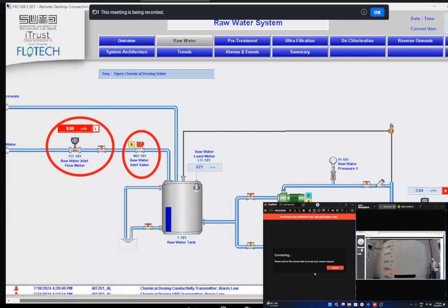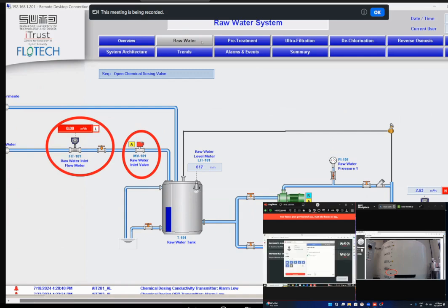On the right, we see P101, which is a pump which is pumping water out of the plant. That's why we see the water level is decreasing currently. So the attack is very simple. The attack basically will turn this valve open regardless of the rest of the components. As soon as the valve is turned open, the water will start flowing into the tank, and as a result the water level will start rising, and in case the pumps are turned off, the water level in the tank will keep rising and the tank will overflow.